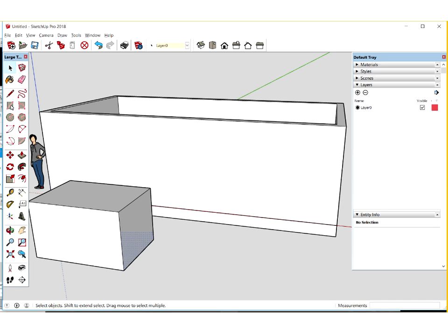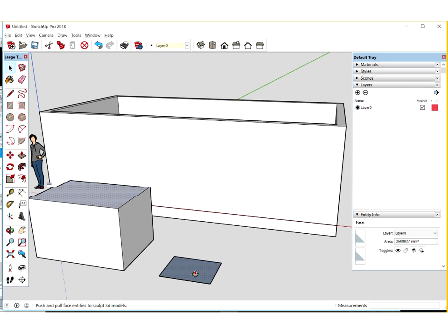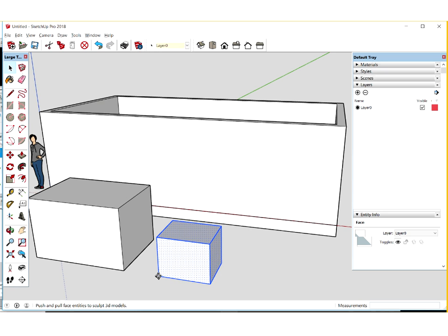So there we've got a box. Then if I build another box, I'm just going to reference that point so they sit near each other. It's called inferencing. If you hover over a point and then just move away slowly, it'll give you an alignment there. So those two boxes are separate objects, so I'll give you some thickness. So if we don't group them together, what will happen, I'll triple click on the second one here, select my move tool, move it over here.